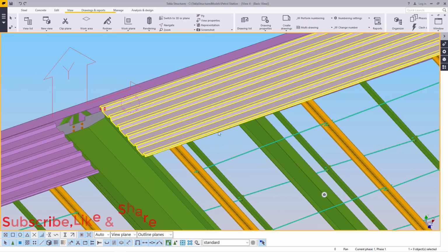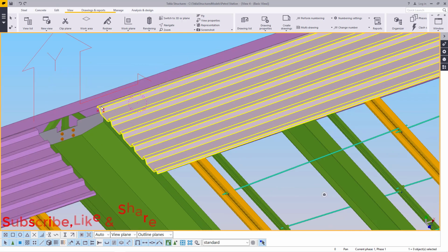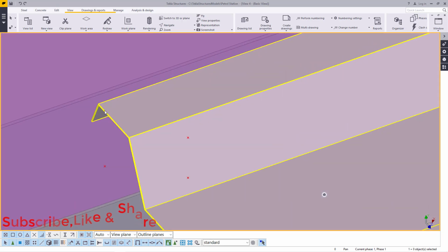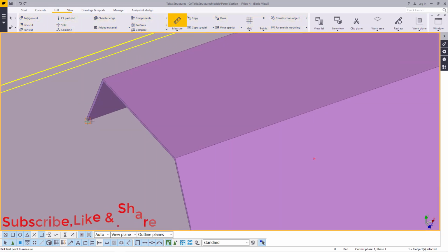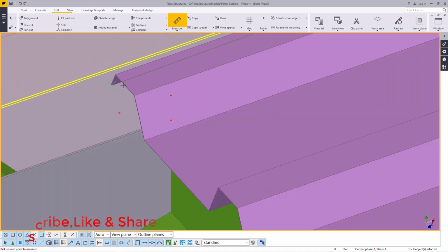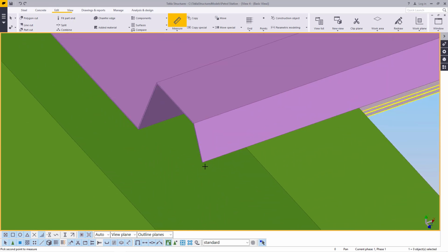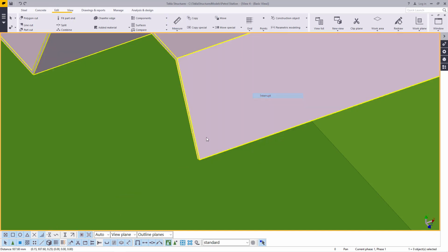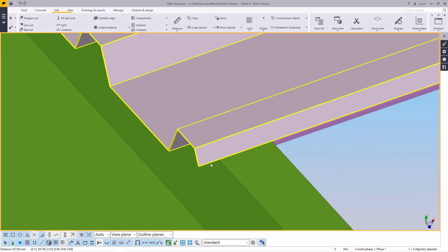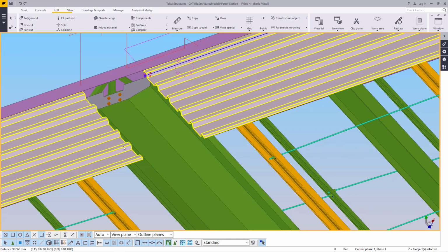So what we're going to do is just select on this sheet, select on that, and first of all, prior to doing that, kindly check the length or the width of our sheet. We'll come to edit and come to distance and pick from that spot and zoom out and check this length or this width. This is 937.6 down here, 937.6. So this is the dimension we are going to use to populate these sheets on top of our canopy.